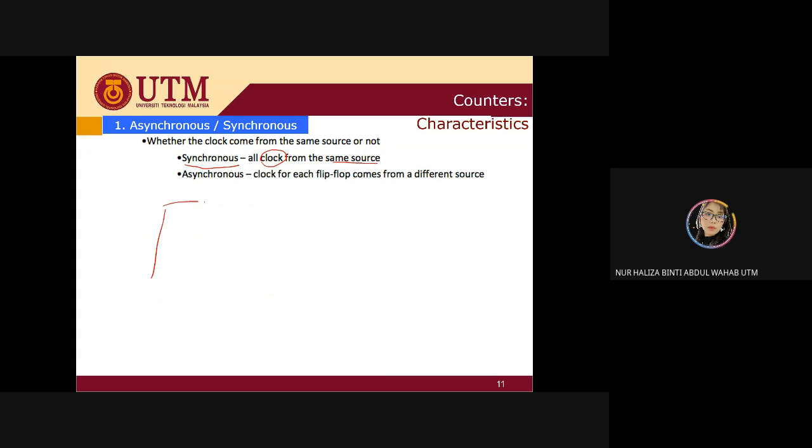For example, if you have only two flip-flops, this is just a normal flip-flop that you can have for your JK. And remember, this is the symbol for your clock. If I have it like this, it means that it is a positive edge, positive clock. And of course, I'm going to have K and J here, 0, 0 for FF0 and 1, 1 for FF1. Why is it 0 here and 1 here?